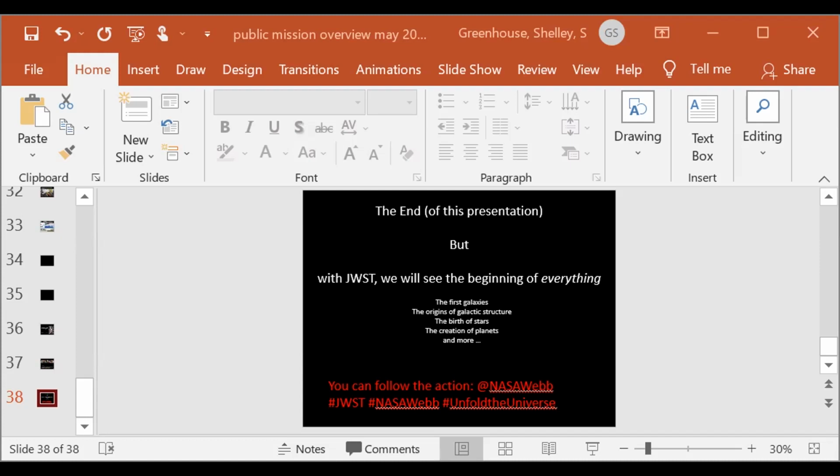All right, the question from Gagan. Are the 5 layers of the sunshield placed at equal magnitudes from each other? Okay, are the 5 layers equidistant? They're at a very precise distance from each other, and the distance changes as you move out in radius from the center to the edge, so that the radiation can escape as it moves out to the edge.